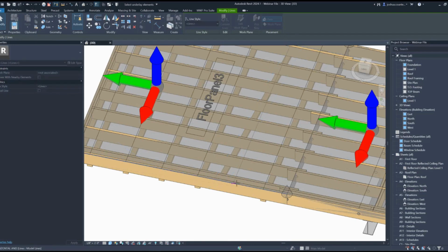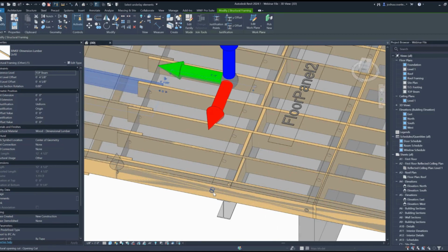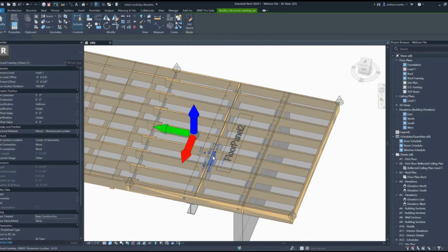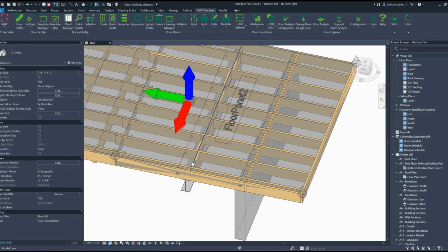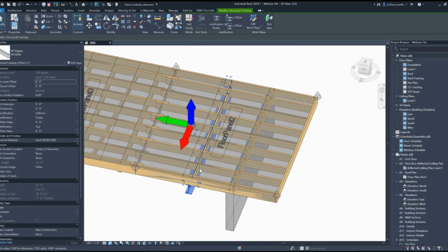You can move around your strapping members. You can apply different hole series. You can create a bunch of different patterns. So you'll notice that I actually utilized the tool 3 different times in this panel. I utilized it once for the wall panel below, and I wanted this member to align with the wall below. I also created one for the I-beam. I wanted blocking to align with the I-beam above, or below, sorry. And then I created another one for this hole series to run through.